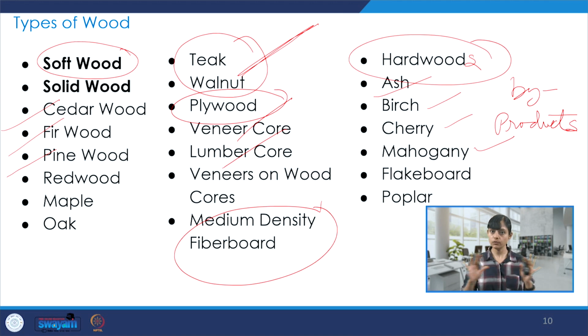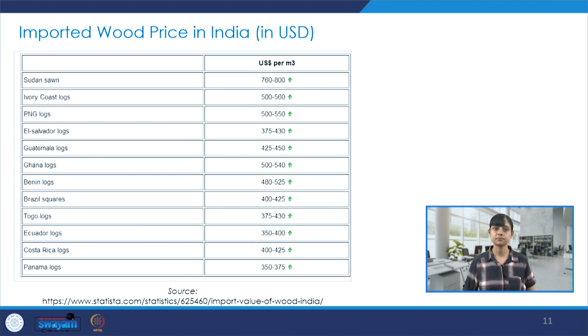So this was an overview, and of course, it will come only after a lot of experience working on site and touching the material, using it, trying to learn through the method of cutting, whether you want to cut along the grain or across the grain. So, along is always more advisable to maintain strength. All of these, theoretically speaking, give us some awareness, but there has to be a practical understanding which will help us understand these materials much better. And then we can utilize them to their full potential and execute them in the best way possible.